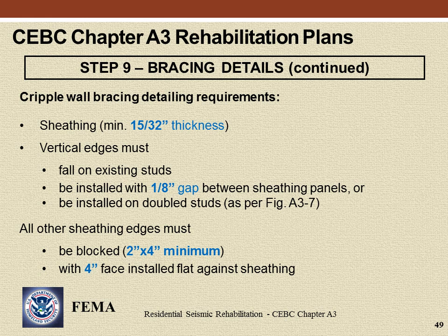15/32 inch plywood or OSB sheathing is a practical thickness to use for cripple wall bracing. Thicker sheathing does not hurt to use, but it does not significantly improve performance either. Nail bending is predominant behavior. Sheathing with exterior exposure rating is highly recommended.